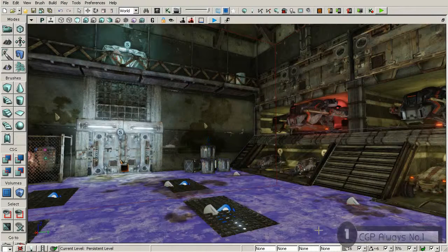Okay. So as we progress through this, you'll also notice that we have an angle snapping. So it gives us an angle that we can snap to, and again, you'll see that we have a couple of different degree types here, and this is going to be very helpful for working inside of our set dressing here. We also have percent snapping, so if we scale something, it's going to scale at a certain percentage.